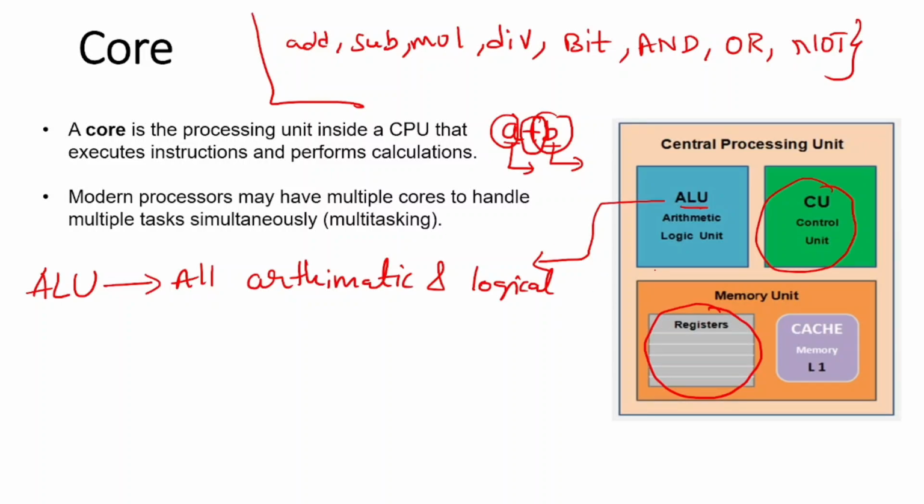See, whenever someone asks you what is embedded programming, you can simply answer that embedded programming is nothing but programming the registers of a hardware. Here remember, registers are a very basic unit, but they play a crucial role, because whenever you want to develop something in an embedded system, the first thing is you have to see what registers are present in the particular hardware module, and you have to know how to program those registers. And if you program those registers, automatically that embedded system will act according to your programming on registers.